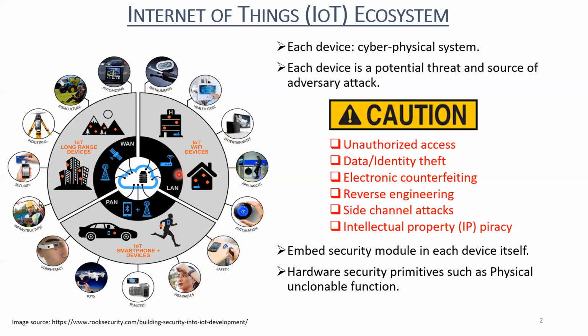So what exactly are hardware security primitives? Hardware security primitives rely on the inherent variations in the CMOS circuit, such as RTN, noise. Then there's this stochastic behavior that your emerging non-volatile memories especially show too much. Even your NAND flash memories, you remember that the programming mechanism itself is very stochastic, and the kind of threshold voltage distribution that you see from device to device is very high. I mean, the distribution is very broad. So these hardware security primitives rely on that kind of variation.